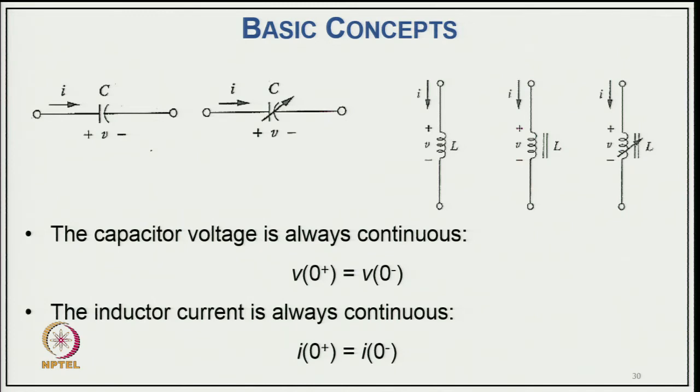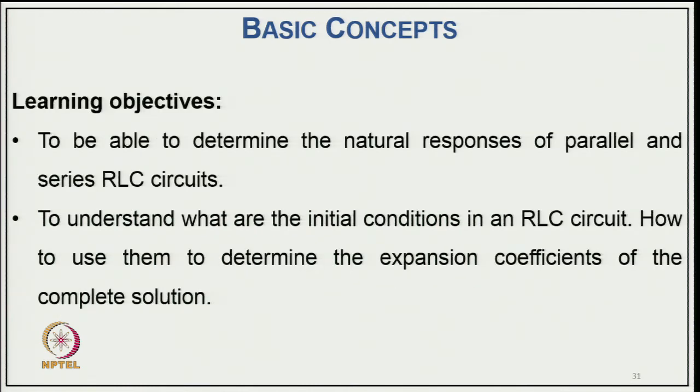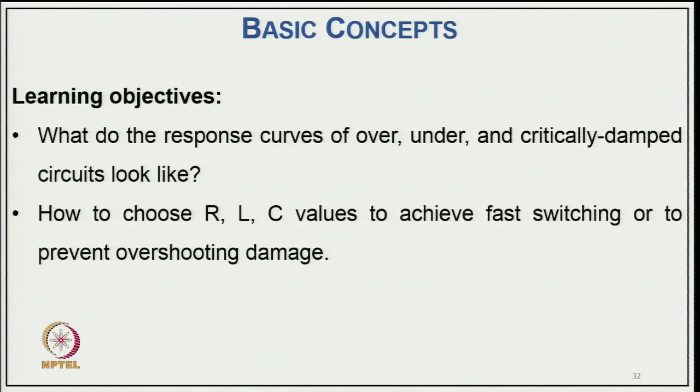Similarly, inductor current also is continuous, it can also not change quickly. So, I(0+) will be equal to I(0-). So, now the learning objective of today: we would like to be able to determine the natural response of parallel and series RLC circuits, and to understand what the initial conditions in an RLC circuit are and how to use them to determine the expansion coefficients of the complete solution.